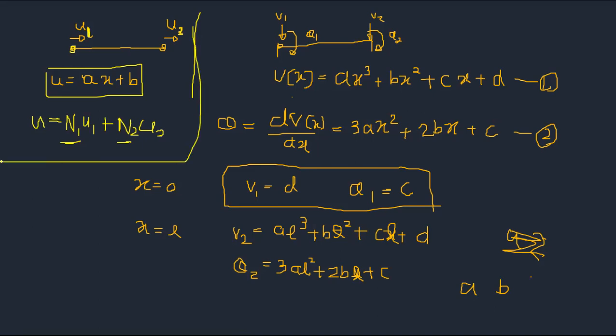Same principle here. You have 4 displacements. That means you can write a polynomial like this: ax cubed plus bx squared plus cx plus d with 4 constants, right? 4 constants you can find because you have 4 displacements, right? So that is exactly equal to the number of displacements. So here it's 2, that's why it is ax plus b. If it was 3, ax squared plus bx plus c. Since it is 4 here, ax cubed plus bx squared plus cx plus d.